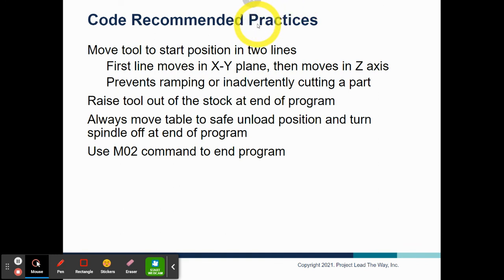So you should always move the machine to a start position, and raise the tool out of stock at the end of the program. That means after you're done cutting, make sure you come up in Z so you're away from the part, and then you can go back to some home position.